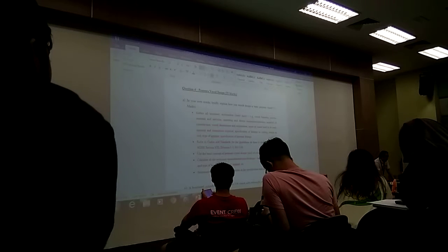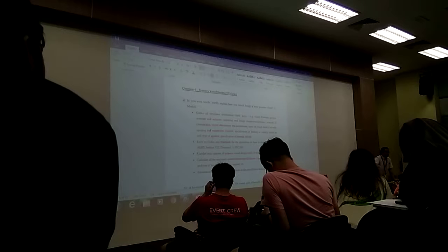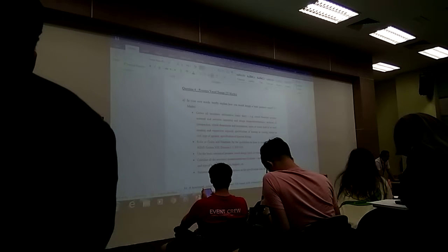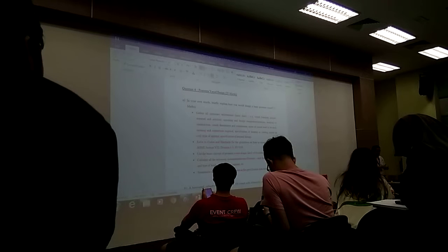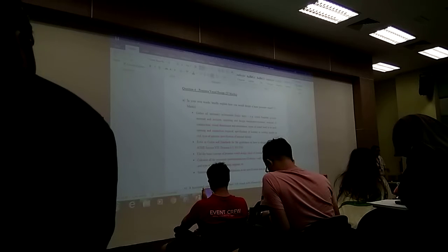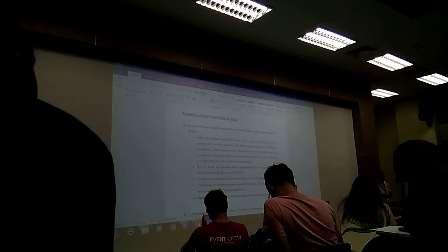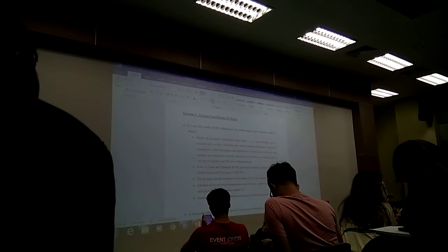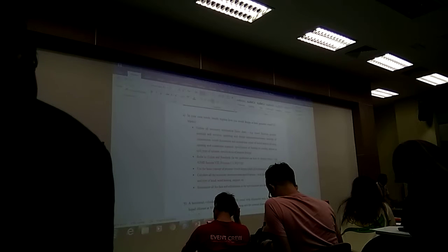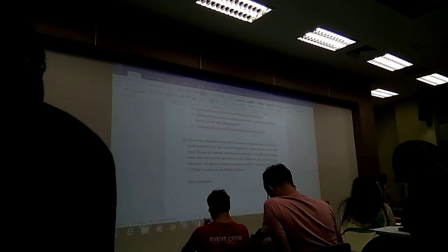Okay? And then use the basic concept of pressure vessel design, which is the shell of revolution, and then calculate all the necessary measurement, specification, example, the wall thickness, the selection and type of the head with load, support, etc. Summarize all the data in the specification data sheet. That is the general way to perform the design of the pressure vessels. Okay?